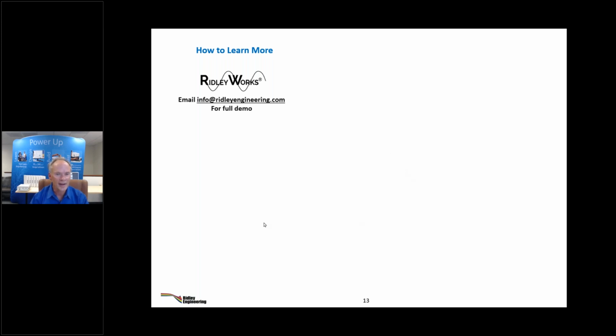And you flagged how to analyze these for interleaved inductor multiphase. I don't know. If it's a multiphase buck, it's all DC, so it's not very exciting, that particular case. Okay. Could you do a Litz wire example? We haven't put that in there yet. You just have to go to the extra layers. We don't do Litz at this point. My advice on Litz is build it with solid wire. If you don't like the results, try the Litz in there. But I'm less than satisfied with Litz working the way it's supposed to, and that's kind of why I've stayed away from that a little bit.